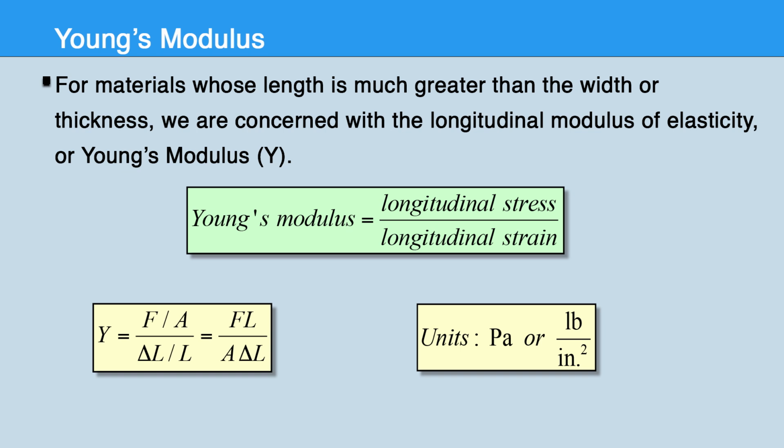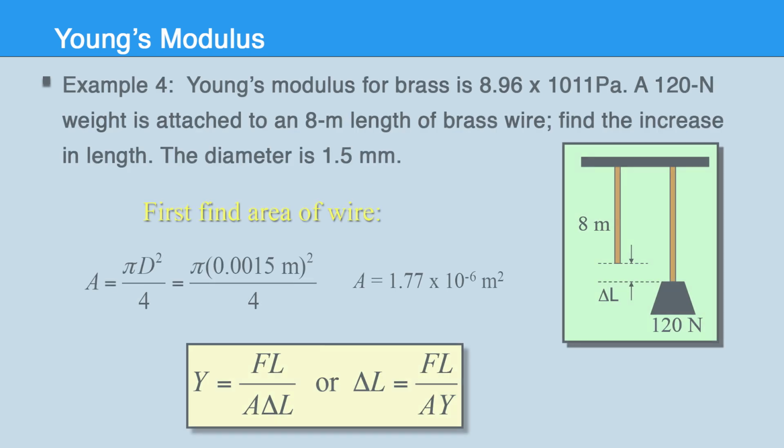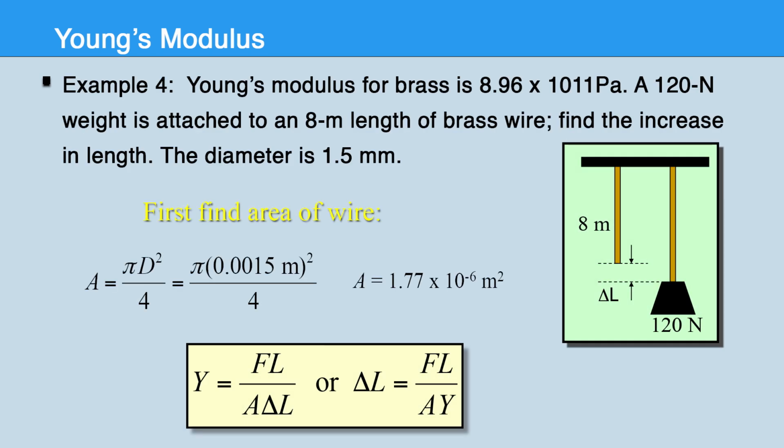First one is the definition. Young modulus is defined as the ratio of tensile stress and tensile strain within the elastic limit of a material. The elastic limit is the maximum extent to which a material can be deformed without undergoing permanent deformation. The mathematical formula for that is E equals stress upon strain, where sigma is the tensile stress and epsilon is the tensile strain.